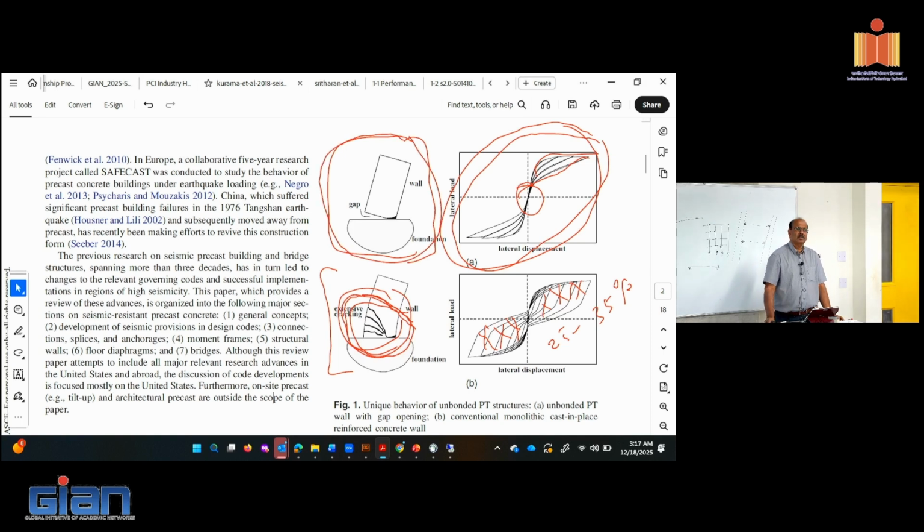this concept was looked at from what they call free rocking structures. In earthquakes, I think a well-known scientist, Housner, came up with a theory for free rocking structures. The free rocking structure behavior is very different from the typical dynamic equation of motion concept. You have to analyze it as a free rocking body. Free rocking structures will go through different motions than what one may call controlled rocking, which I'll get into some more tomorrow or so.